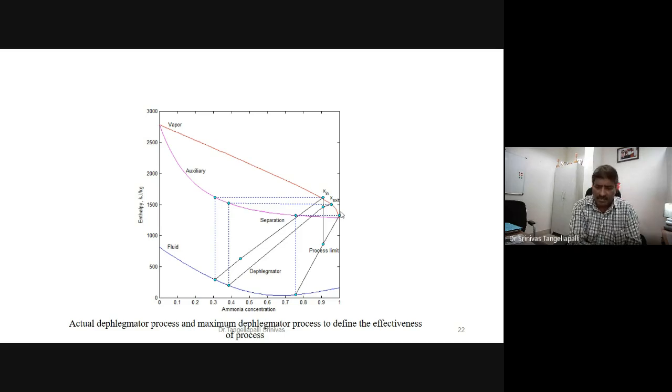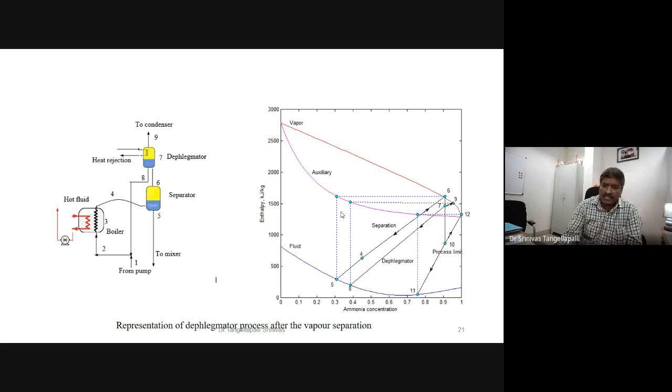At the same time, of course, we get some benefit for the cooling system, but in a power generation system there is a loss in power because some of the working fluid we are removing. See here, a condensate is coming out without entering into the plant, maybe cooling plant or power plant. Some of the working fluid is returned back to the boiler without doing any work, any cooling task or power task. So that is the loss.